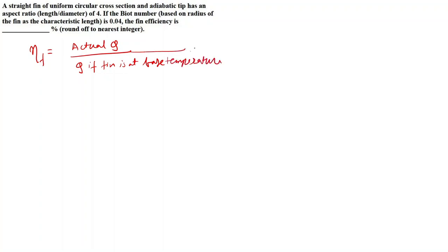Okay, so we define this fin efficiency as η_f is equal to the actual heat transferred upon Q if the heat transfer of the entire fin were at base temperature, that is, if the fin is at base temperature.